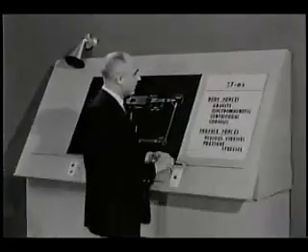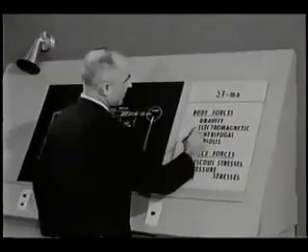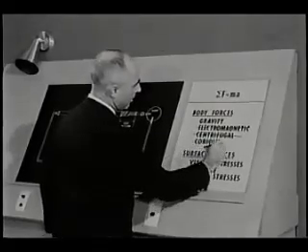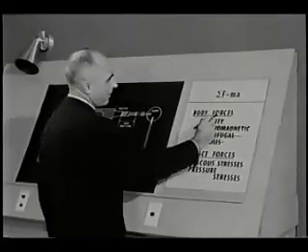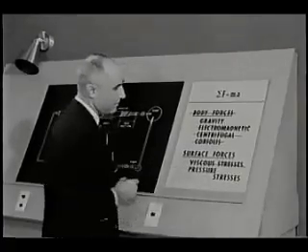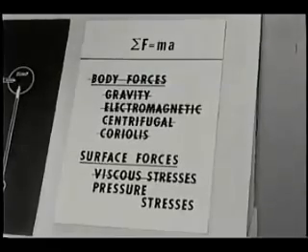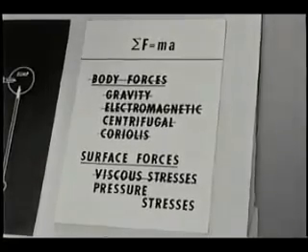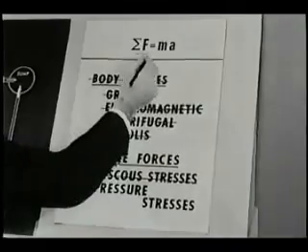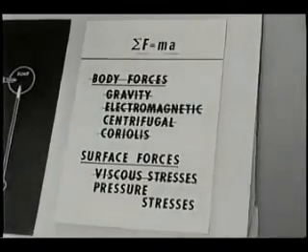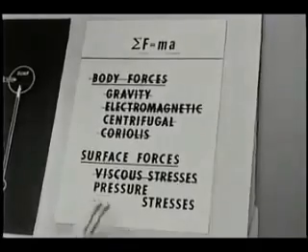we have designed experiments in which gravity, electromagnetic, centrifugal, Coriolis, in fact all body forces, as well as viscous forces, are relatively unimportant. The centrifugal and Coriolis forces referred to here are present only in rotating reference frames. The main force, accounting for the fluid acceleration, will be due to normal stresses, to pressures.